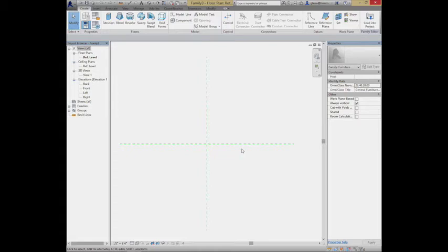If it's all very squarish and perfectly vertical, extrusions are great. If I want to have more of a taper, I can lean back, and I might do that as a sweep as opposed to an extrusion. This might be a sweep that comes along like this. My handles will probably be about the same. I'll probably still do those as extrusions, or my arms, on both sides. But let's go for this. We'll go for that to make it real simple as a starting point. We can morph into that.